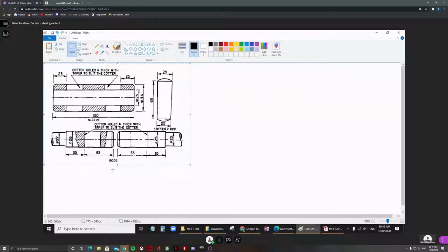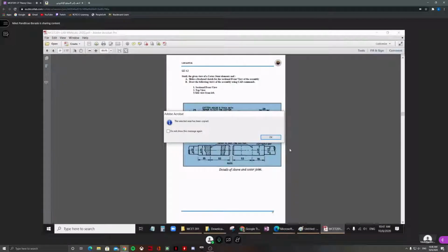Then the two rods are given, and we have to understand the shape of the part. Then we think about how to assemble them. Then we think about the dimensions also. Now there is a diameter 25 hole in this part. That means the diameter of the rod also is 25, and it may not be clear in this drawing.